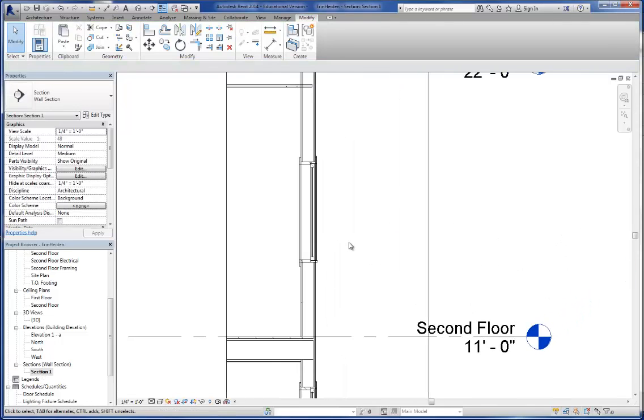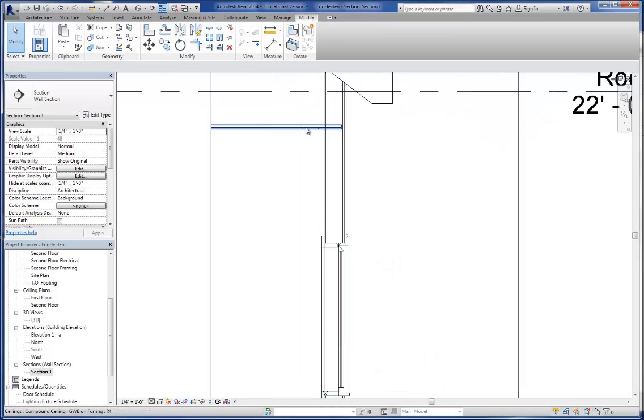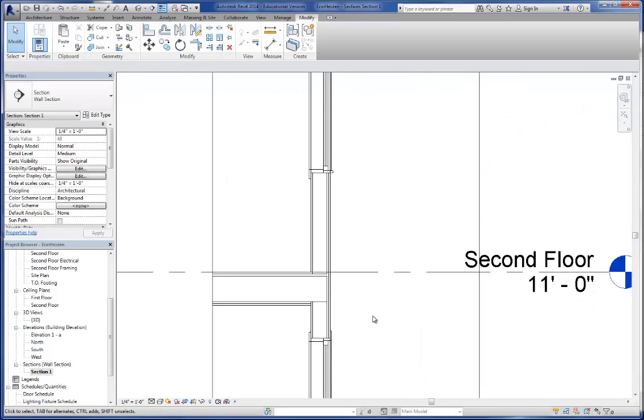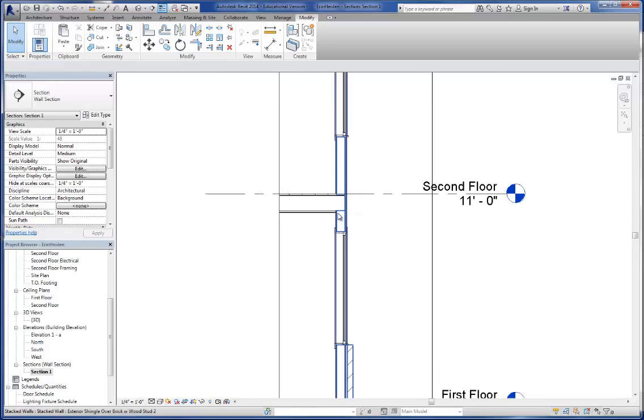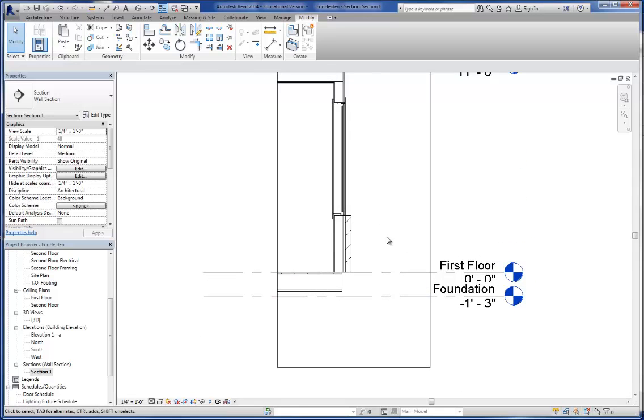Okay. And so that's really, really easy, basic technique for going through and setting up. And you can see we can do the same thing up here. We can probably insert some finishes, and we'll get to that here in a bit. All right, but that's basically how you guys are going to go through and modify and do the stack walls and get your connection details to fit. All right. The next thing we're going to go through is actually setting up and developing the foundation here.